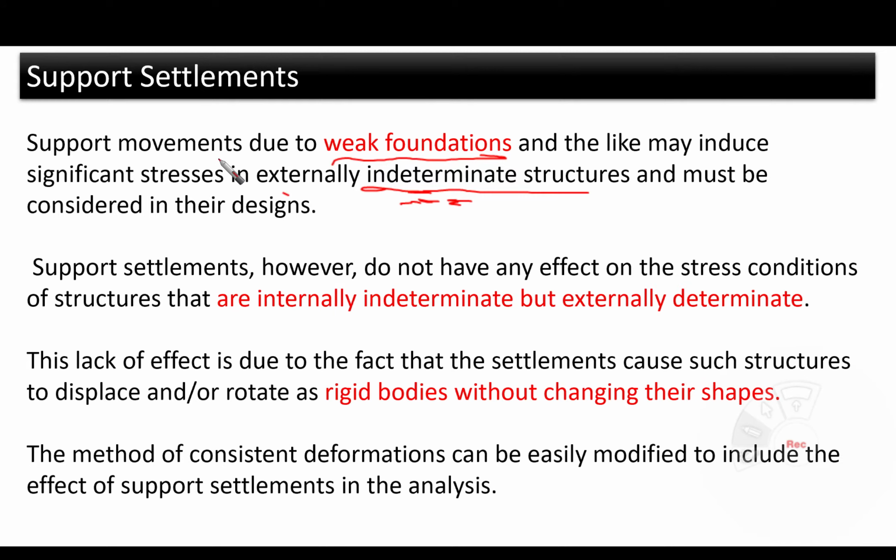Okay. Support settlements, however, do not have any effect on the stress conditions of structures that are internally indeterminate but externally determinate. This is an important issue: we need to differentiate between internal indeterminacy and external indeterminacy. Whenever we are thinking about internal indeterminacy, support settlement has nothing to do with it.